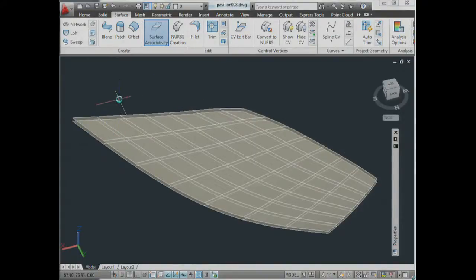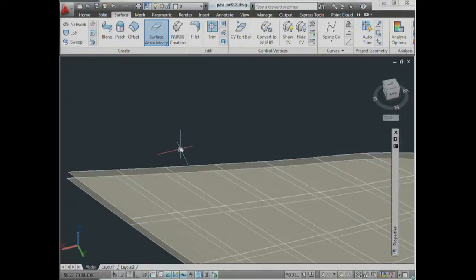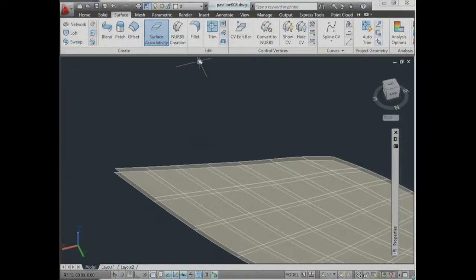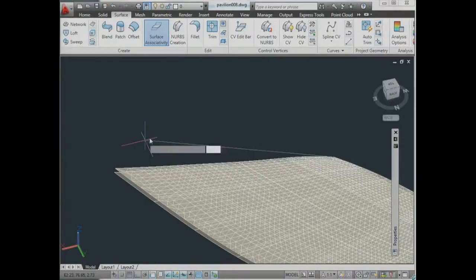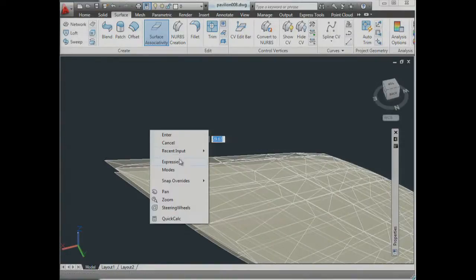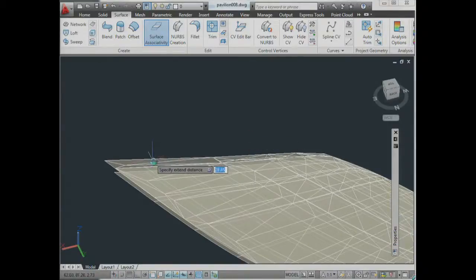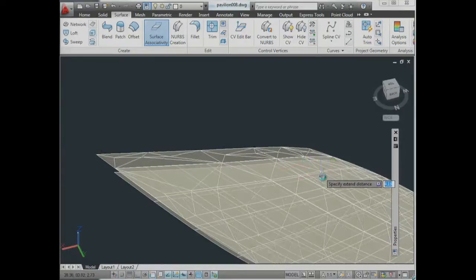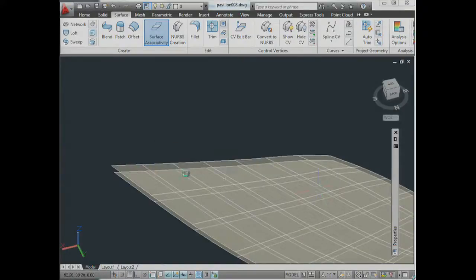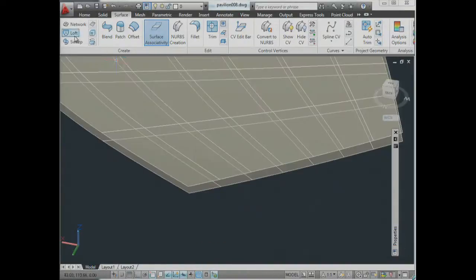In this case, I'm making an offset of the roof, and let's say I want to extend one of the surfaces, so it's not exactly a thicken operation in which it's just thickening through the parallel, right? It's really something that has two different surfaces. So I want to extend one of the edges because I want it a little longer. This is what I'm doing with the Extend command on surfaces. I'm getting the feedback exactly of what's happening and where I'm going with the surface. So right now I have one surface slightly longer than the other one. So Thicken here would not work.